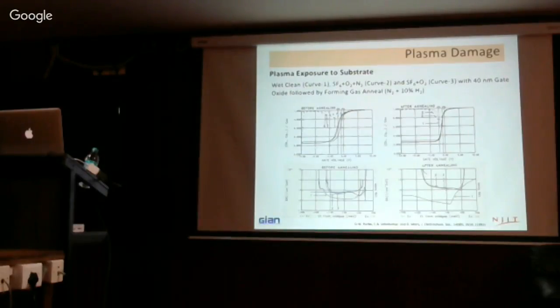Okay. Especially when you have a very sensitive device, even the series resistance comes from the leakage current. Measure the leakage current. That is the best way to know. Those who have low leakage current, you will see that the change in accumulation capacitance as a function of frequency will be much less. For large leakage current, the change will be large.